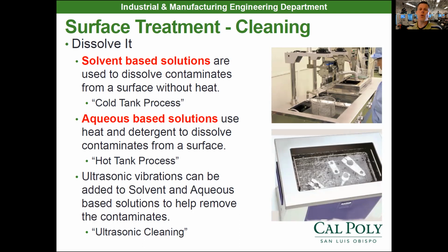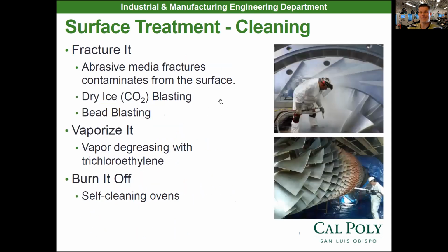Now, if you've ever heard of ultrasonic cleaning, you can add ultrasonic vibrations to this aqueous-based solution, basically vibrating it at high frequencies. That bit of mechanical vibration helps the aqueous-based solution break down below the dirt particles and remove them from the surface of the workpiece. So we can dissolve it somehow, or we can wash it.